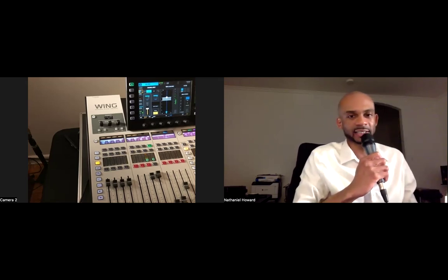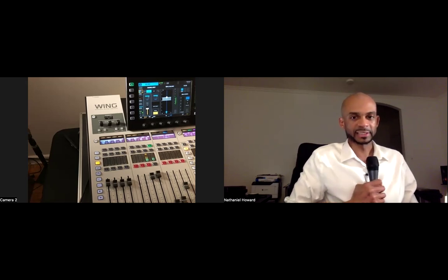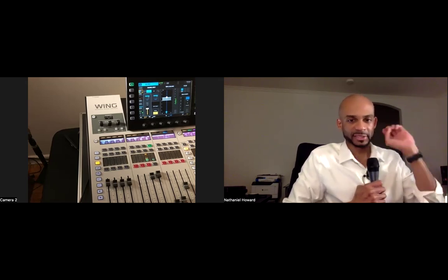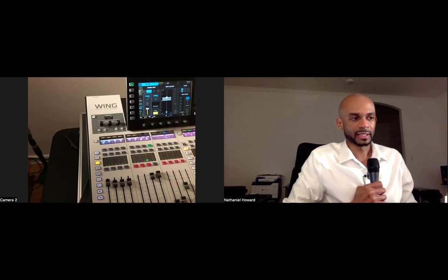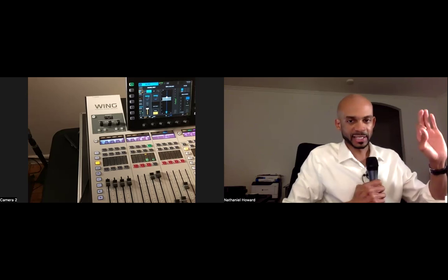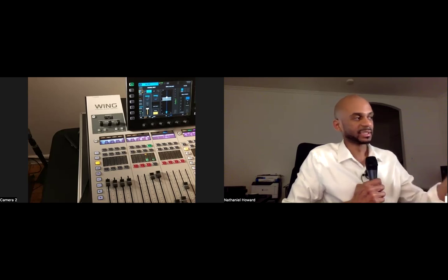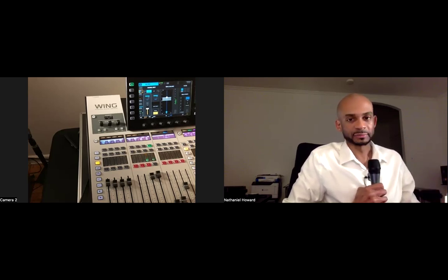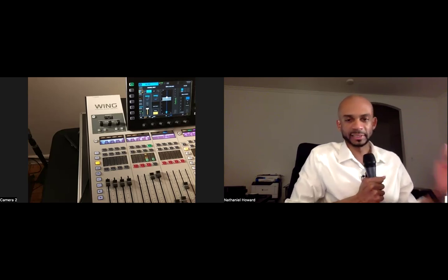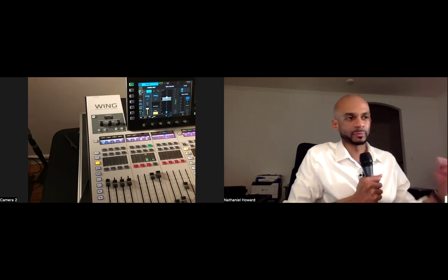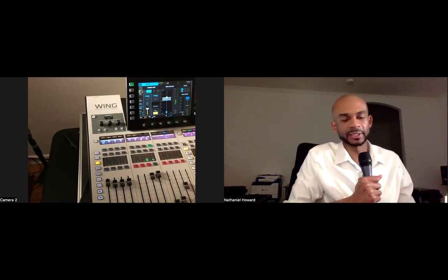So what I did is that I set the gain structure while saying mic check 1 2 from down here, since this is their normal way of holding the microphone. This is what fit that environment, the conference room. So since this is where everybody held the mic, this is where they're comfortable, I raised up the gain even more than what you saw me do over there, to get to -18 on that channel strip. So it depends on the environment. Sound engineers have to adapt to environments to do things that work best for that place that they're working in.